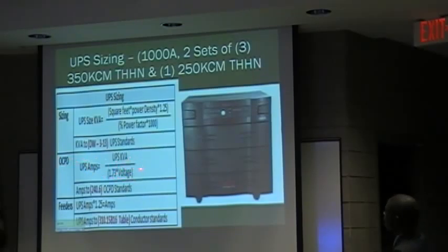And here, when you size your UPS by plugging in the parameters, I believe we need to multiply by 1.25 for the continuous duty, and you need to step up. Whenever you check, we want to check the next standard for it at code book 240.6. You go to the next standard up, and we size the feeders based on code book 310.15(B)(16), as Dustin has rightly said before.